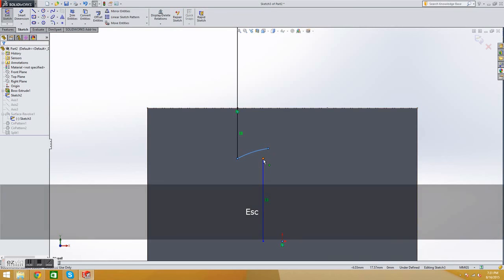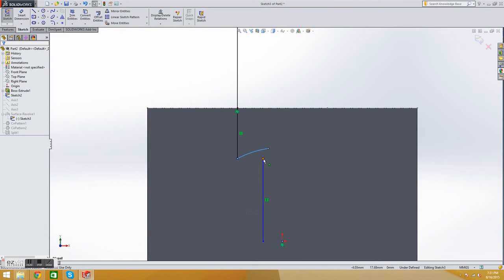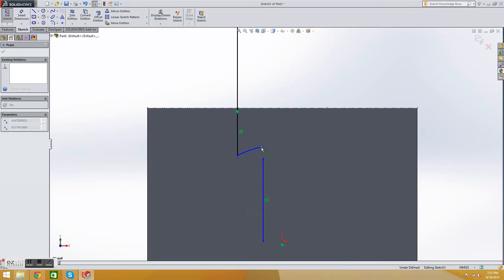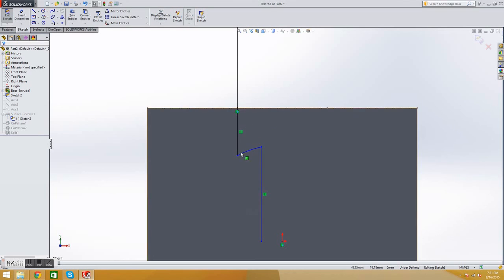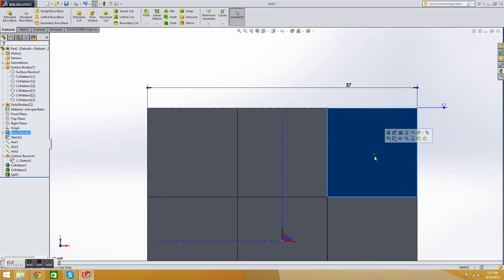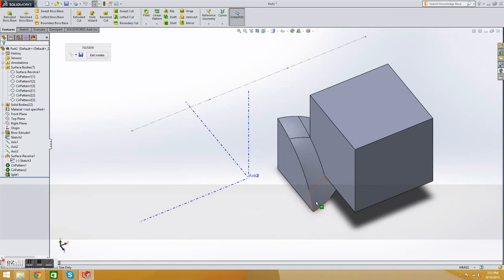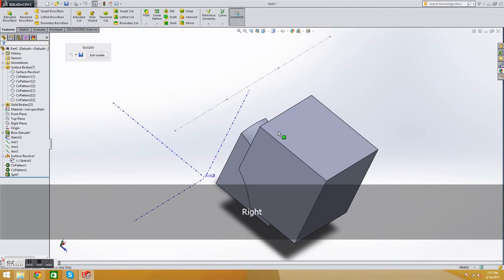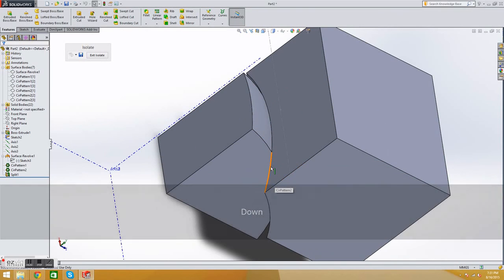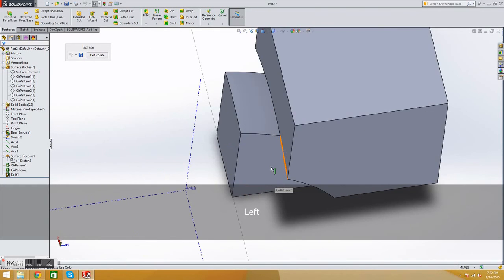So now instead of that line, we have an arc, and what you can do is line it up and then merge these points. So it looks very similar, but instead of there being a line here, there is an arc. Now if you notice, we'll save this. When it rebuilds, you click on this, you press isolate. Notice this here is smooth. There's no more line like that. Notice on this edge, there's not this little shard here. There's not that little thing that was sticking out earlier.